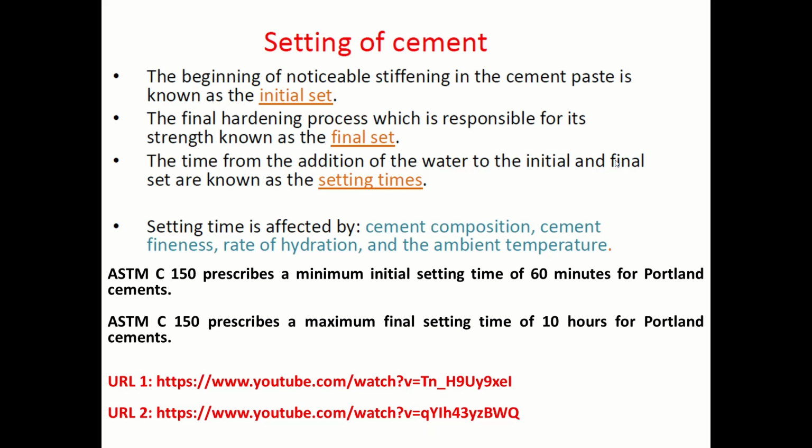For the initial setting time, what is it? The initial setting time is the beginning of noticeable stiffening in the cement paste, and the final hardening process, which is responsible for its strength, is known as the final setting time. The time from the addition of the water to the initial and final setting is known as the setting times.